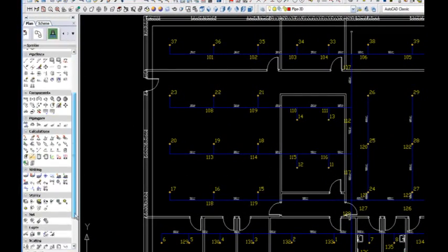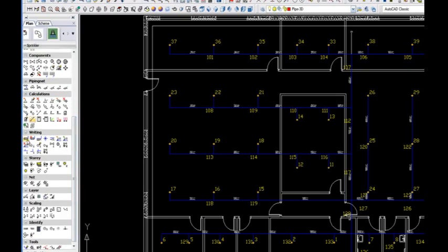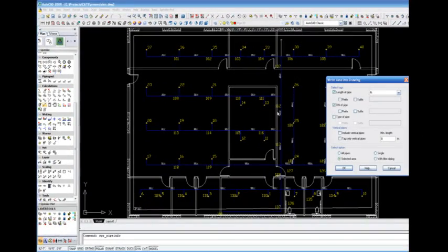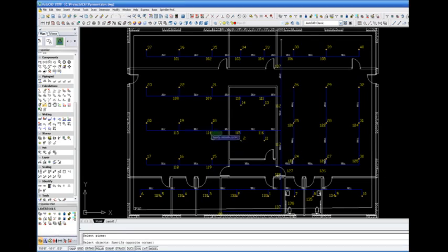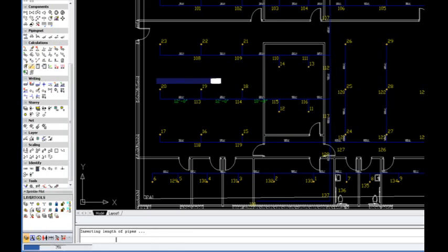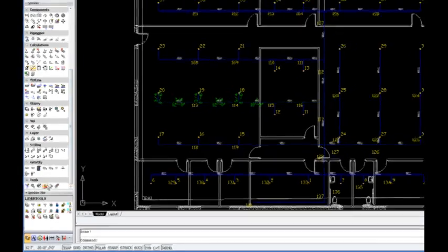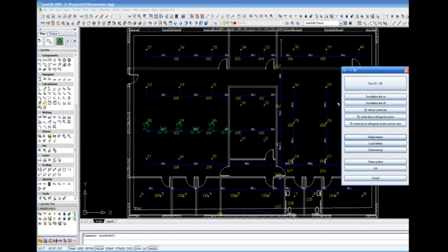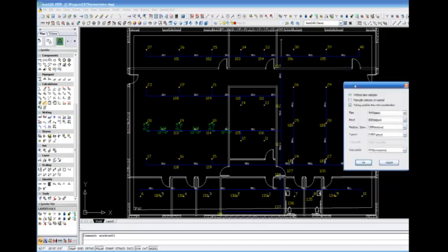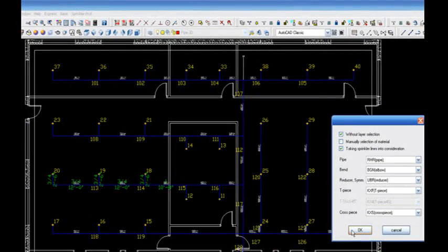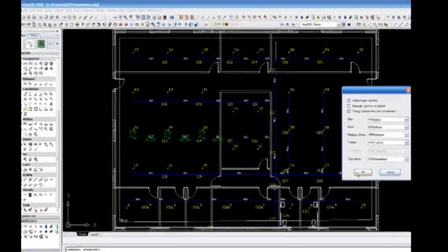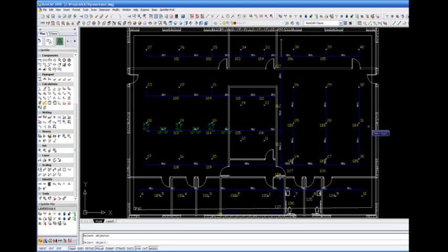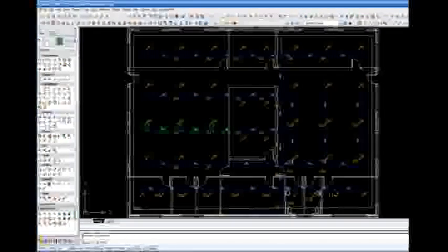In the C.A.T.S commander, select the 1D to 3D command. The software database defaults will appear. You may change the values or select OK if the default values meet your design criteria. Highlight the section of the drawing that you want converted to 3D, generally the entire space. You are prompted to select the radius specifications for the elbows you are using. The default selection will be a standard radius 90. Choose OK.